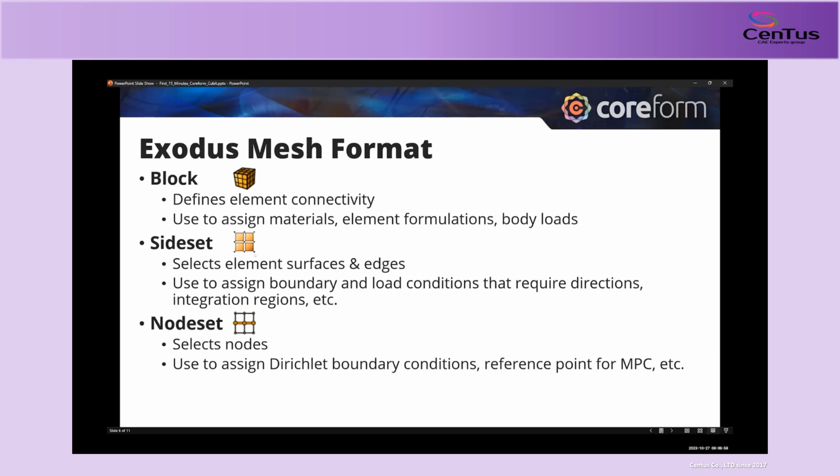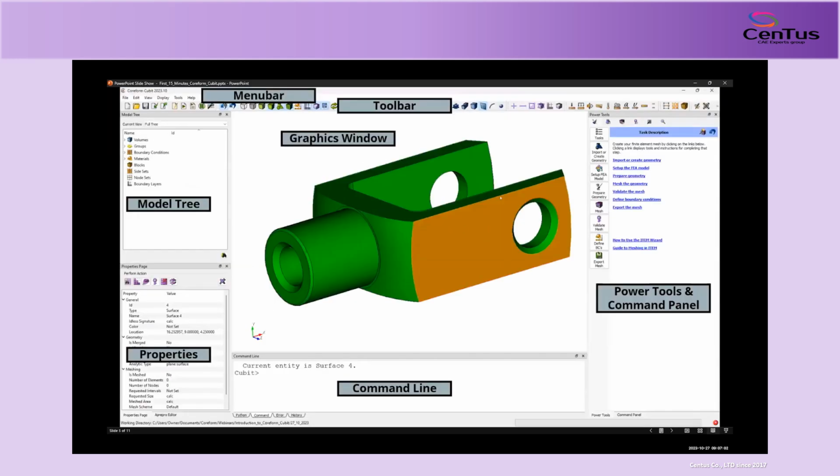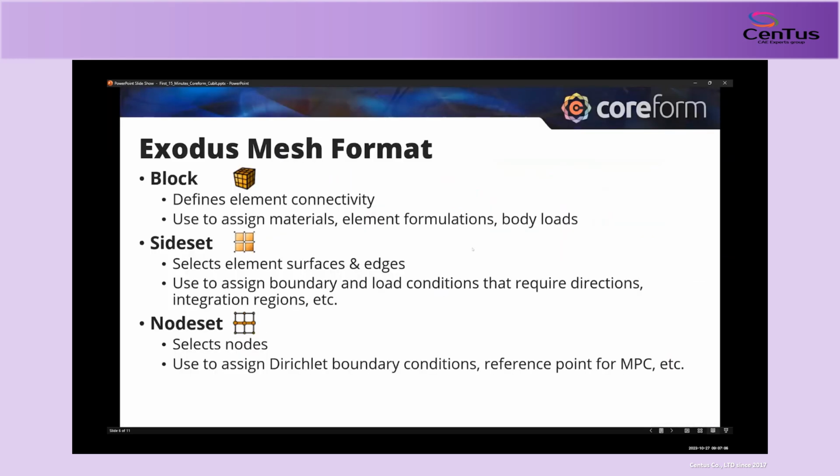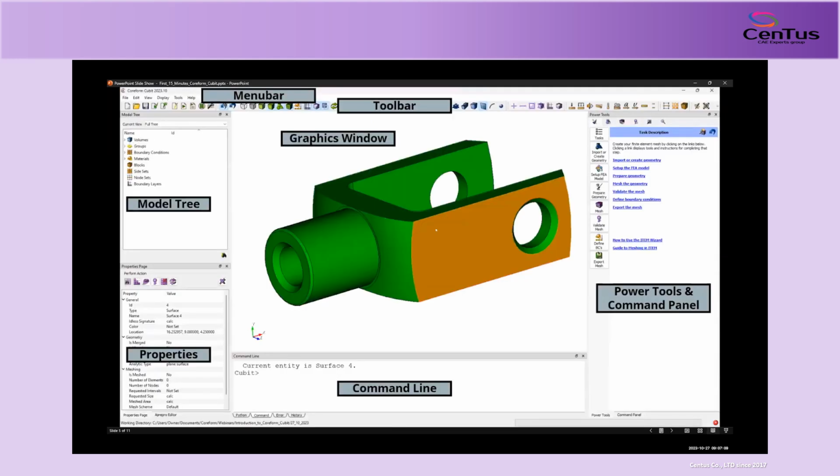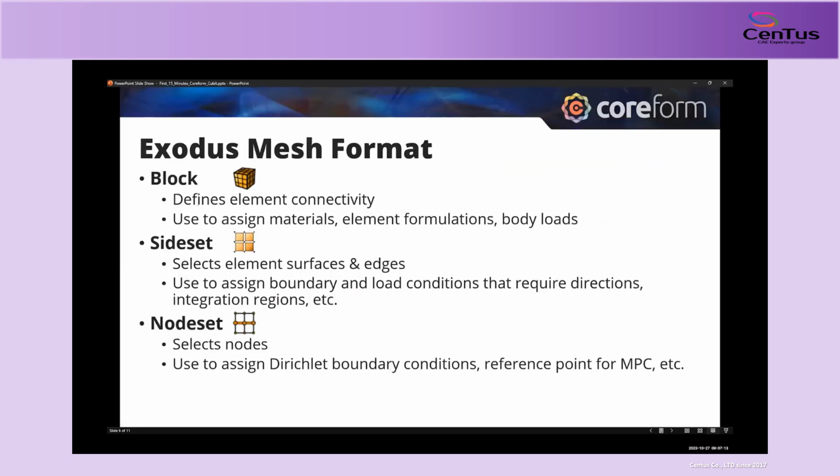While you can pick the individual mesh entities themselves, you can also make sets out of the CAD surfaces, and then when they're meshed, if I assign a side set to the surface, it will automatically grab the elements, or the faces, that are in that surface.